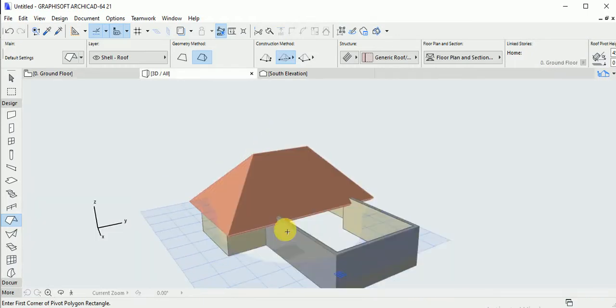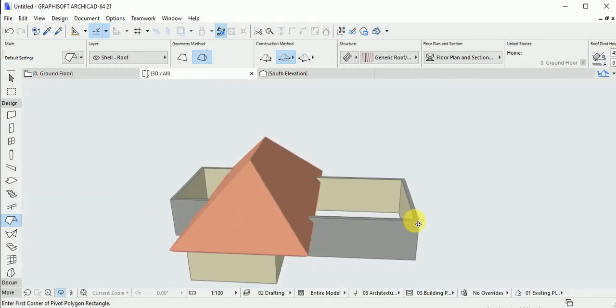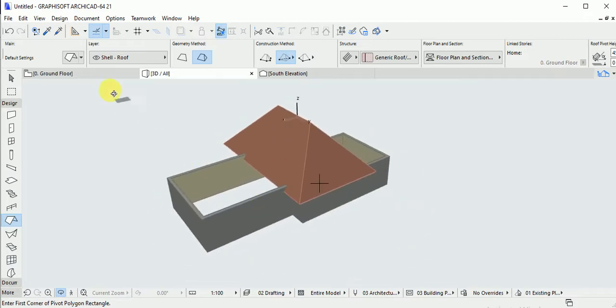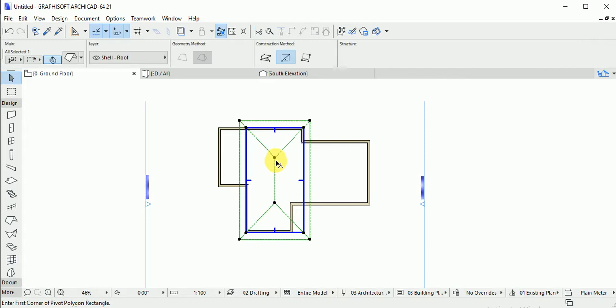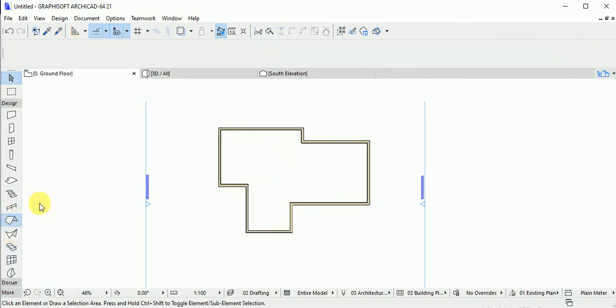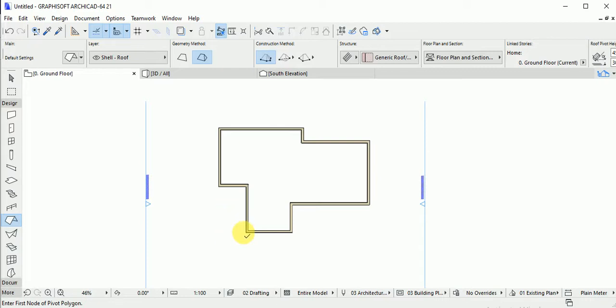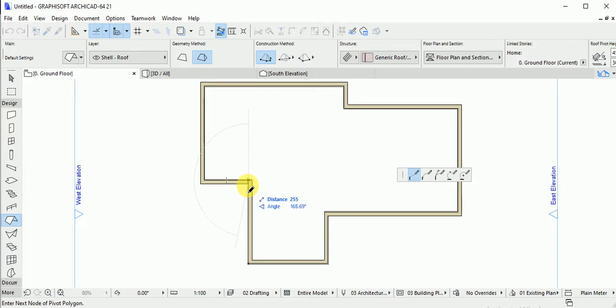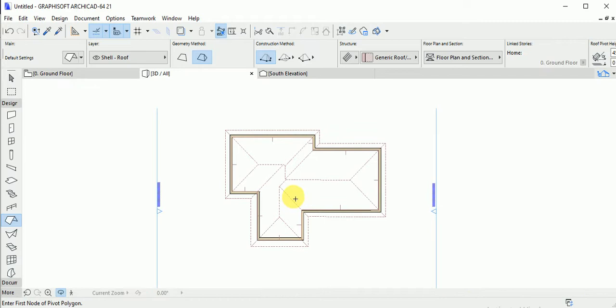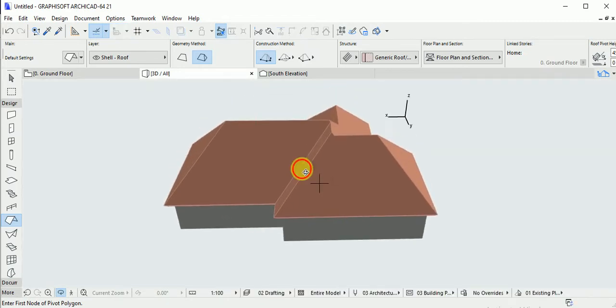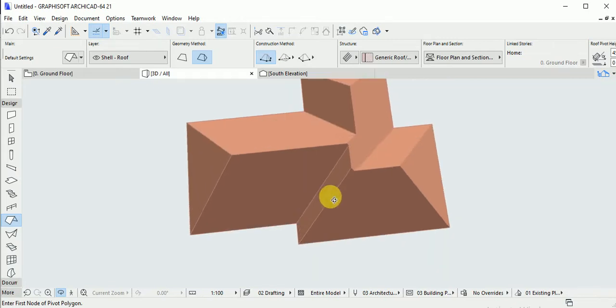Once you check it in 3D, you see this one did not take the shape of the roof at all. I'm just trying to show you another method. Let me assume that I delete this particular roof and still touch on this flat roof, and I still use this line gradually to follow the roof. This is another method too. I'm just trying to take the shape of the wall, all of it. Click it. Now you see this is a roof for you. This is another roof, but I don't want to use this method. All of them will arrive at the same result.